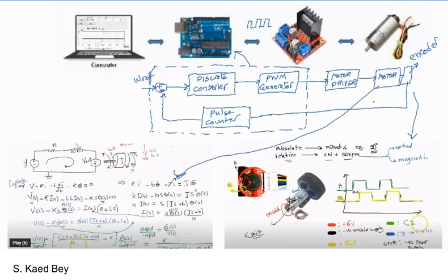The best way to find out the encoder pulses per revolution is to run Arduino code that counts just the encoder pulses while rotating the motor by one revolution. You can do this by hand multiple times and take the average.